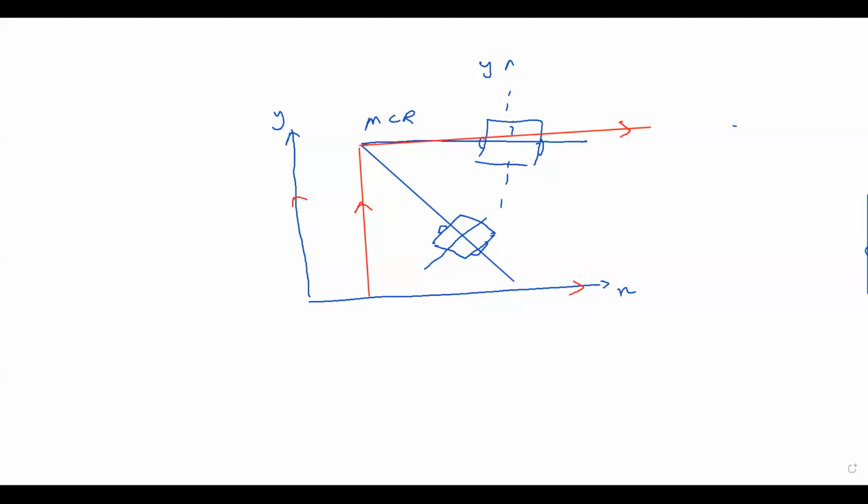And these two lines are going to create two angles, theta 1 and theta 2. I will explain how these angles come about. The only given data for us is this angle, beta, which is something that we are getting. And we can get these two angles. This is the head of the robot, the turning angle of the robot. Theta 1 and theta 2 are input angles. These we get from varying the RPMs of the robot's wheels.